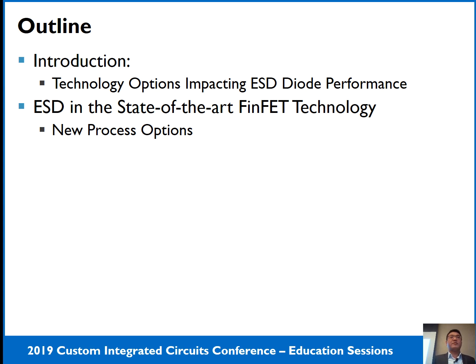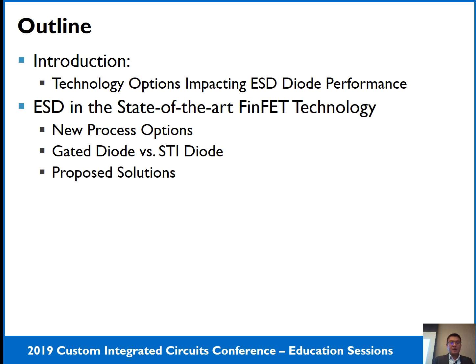I think part of them were already covered in this morning's presentation. Then we will compare two different ESD protection diodes, the gated diode and the STI diode. Then we will also look at the proposed solution to further enhance the ESD diode performance in FinFET technology.